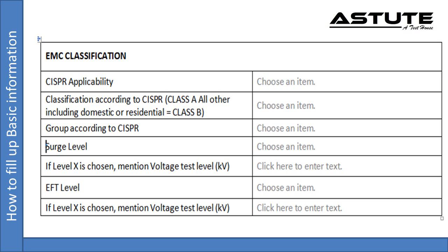Class 1 is a partly protected electrical environment. All incoming cables to the room are provided with overvoltage, primary protection. The units of the equipment are well interconnected by an earth line network, which is not essentially influenced by the power installation or lightning.